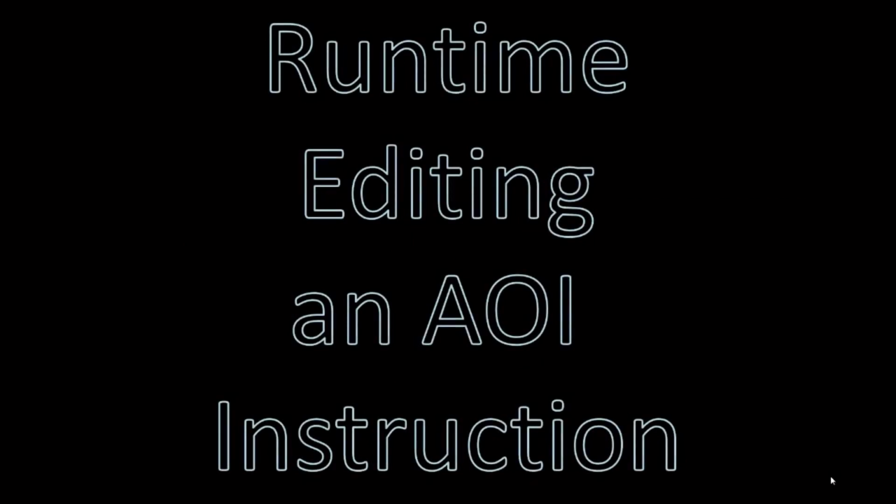Also, runtime editing of an add-on instruction. Add-on instructions can only be edited offline. I guess that's all there is to say. If the intended functionality needs to be changed in a running controller, consider carefully if an add-on instruction is suitable.